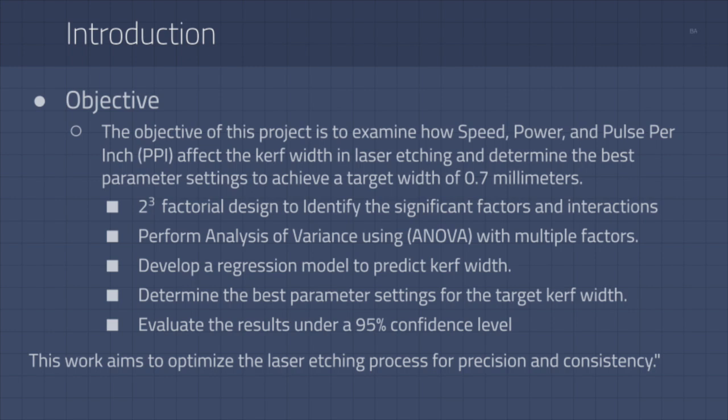Develop a regression model to predict kerf width. Determine the best parameter settings for the target kerf width. Evaluate the results under a 95% confidence level with a significance threshold of 0.05. This work aims to optimize the laser etching process consistency.